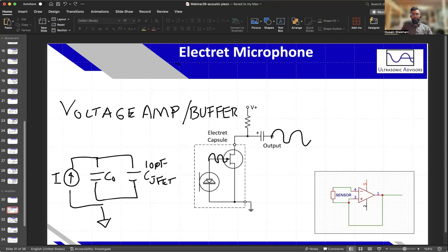I want to bring to your attention something interesting, because I started becoming curious about this, and because we have the electret microphones, those small microphones that are relatively simple to purchase. They kind of look like this. They basically have a dielectric element which has been polarized, so it has piezoelectricity. When the sound comes to it, it changes in shape a little bit, and that change in shape also generates a charge or a voltage on this little capacitive element. So this is not PZT, it's like a polymer, and there are some trapped charges which cause the piezoelectricity of it. Those are the typical things when you plug a microphone into your computer. That is the type of microphone it's using.